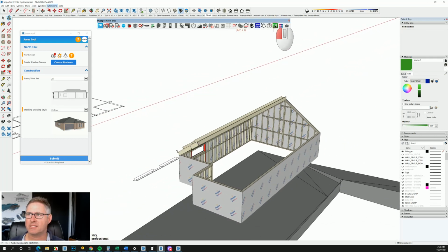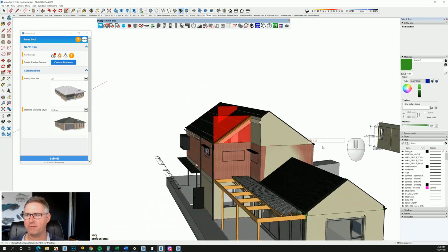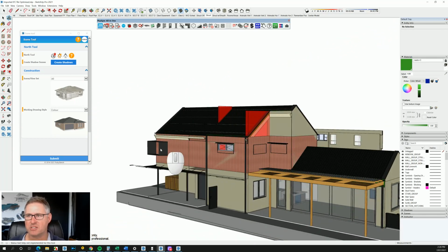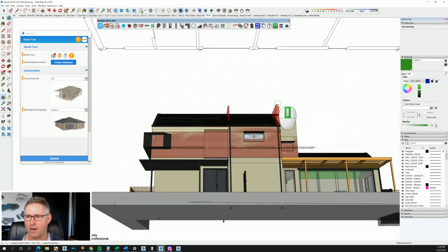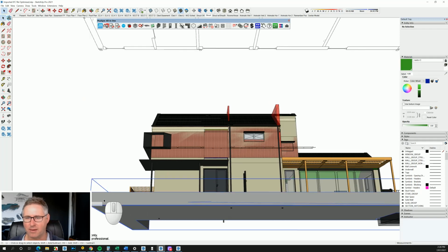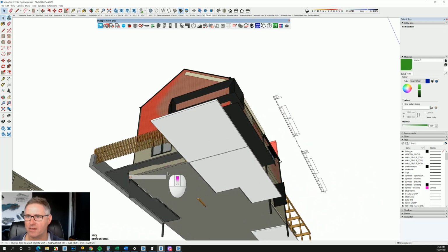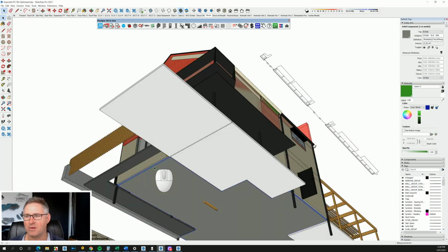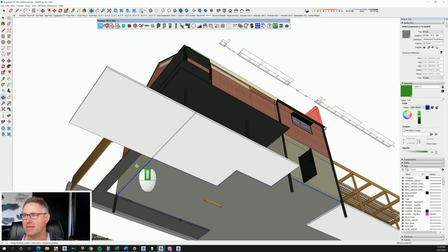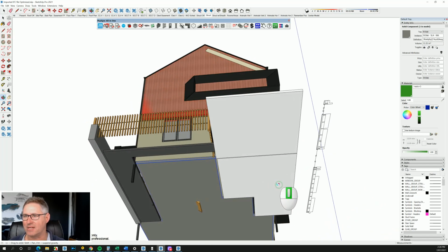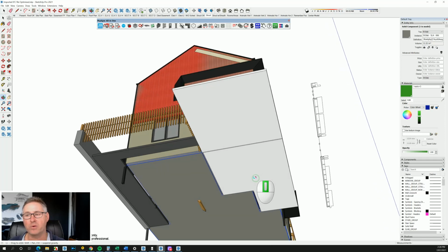Okay, so I'm going to go back to see all, and we're just going to go into this a little bit further because that's repetitious. If I keep doing the walls, you've seen it before, but I'm going to get rid of my block here, hide, and we're going to go in and also attribute our concrete. So if I select that, you'll notice that it's on IFC slab. So I could go through and turn off all of my IFC layers. Essentially now that I do that, you'll notice that this has a volume associated with it.